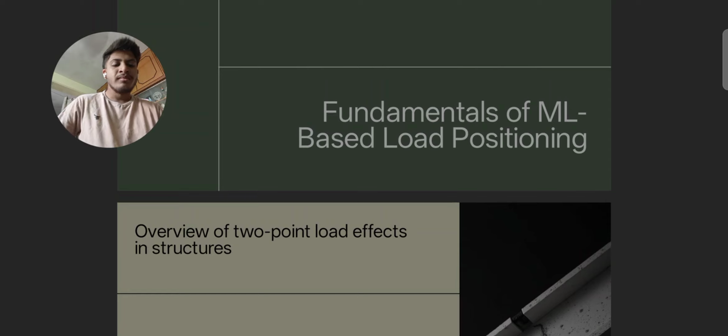deflection. A moving load is a load that changes its position along a structural member, such as vehicles on a bridge or trolleys on a crane runway. The maximum effects do not necessarily occur when the load is at midspan or supports. It depends on the interaction of the load positions and the structural response.